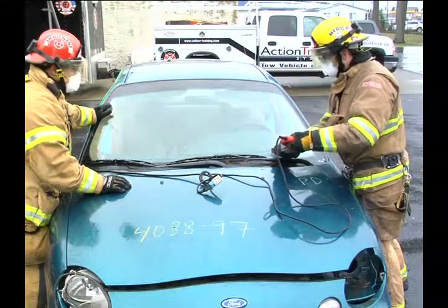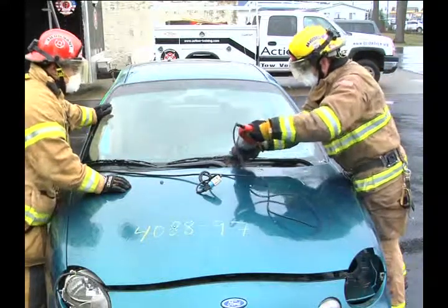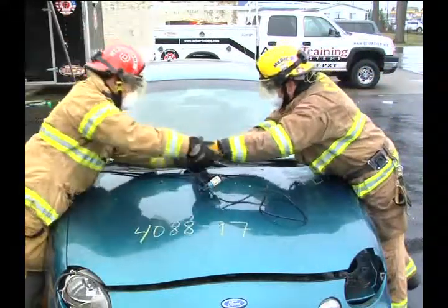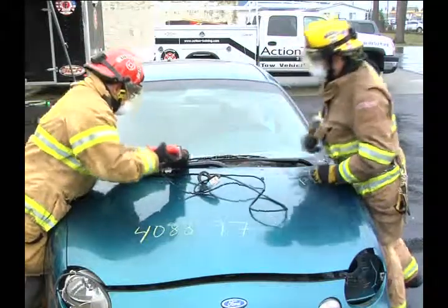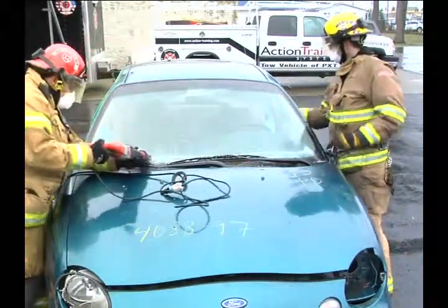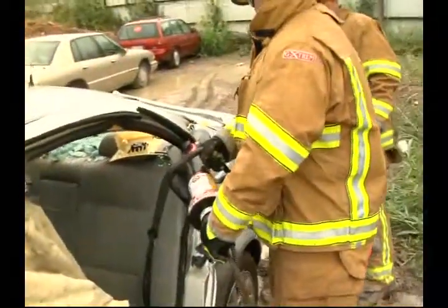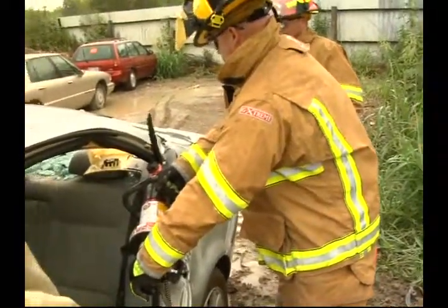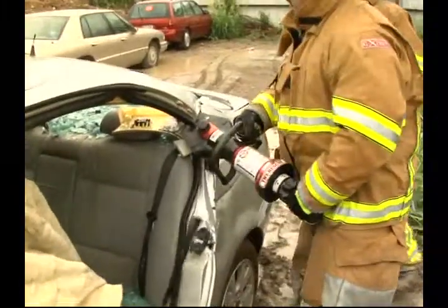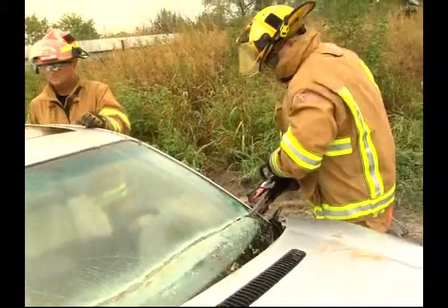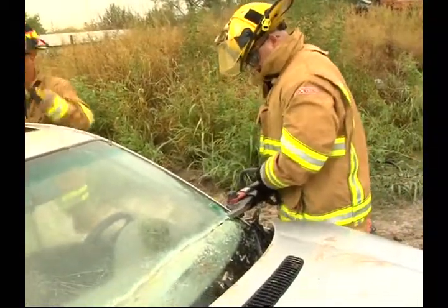If you are going to remove the windshield along with the roof, make a horizontal cut along the bottom of the windshield with a saw from the base of one A pillar to the other. Once you have cut every roof pillar except the front A pillars, stabilize the roof using your crew before the final cuts. Always cut the A pillars last, ending with the driver's side pillar.